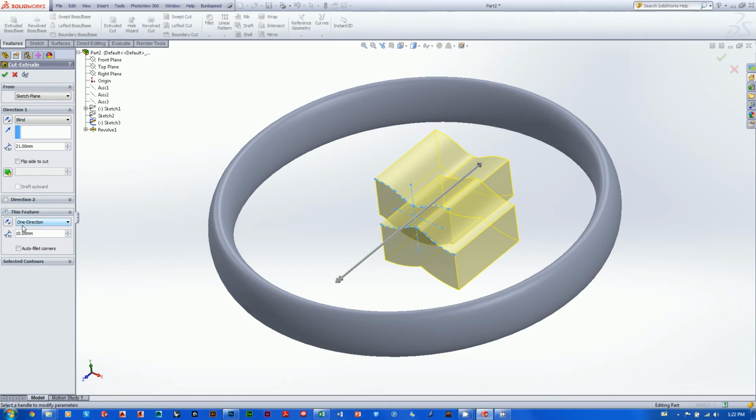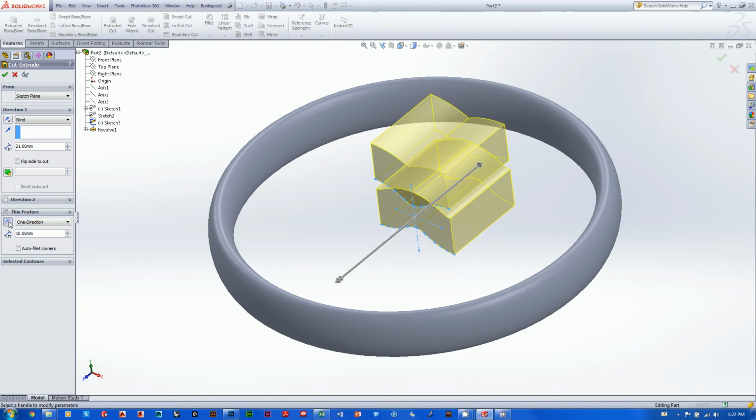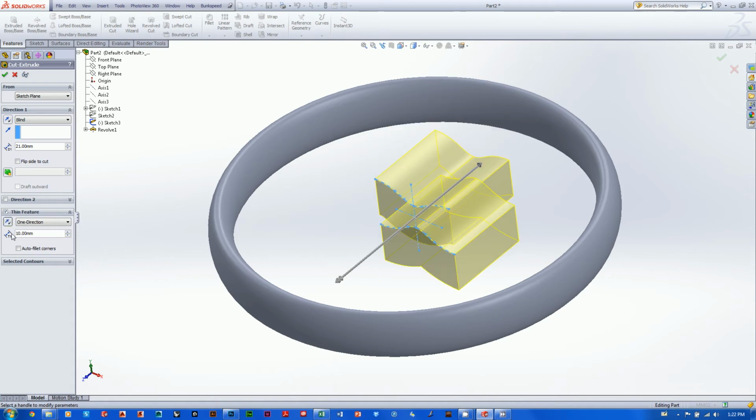Now I also notice here that if I hit this reverse direction button, that shape flips upside down back and forth from one way to the other. And I notice that there's a depth or a thickness of 10 millimeters. So if I adjust that to say 2 millimeters, that's our problem. See, I realize it's adding a thickness to each one of these lines, where in fact I just want to extrude out each one of these lines and take a little sliver out of my piece.